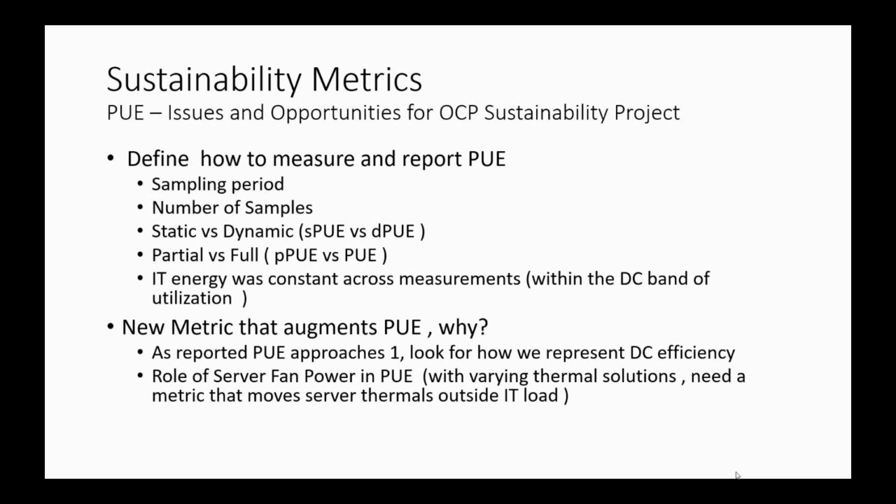when they started this PUE back around 2006, 2007, something like that, you're lucky to have a PUE of 2, right? So you're basically 50% efficient, if you will. Now, everybody that reports PUE, like if you look at the big hyperscale data centers like Microsoft or Google or whatever, they all report close to 1.1. And PUE, the ideal number is 1, right? There is nothing below 1 in the way it's defined. Once you get to 1, you basically are asymptotically done.